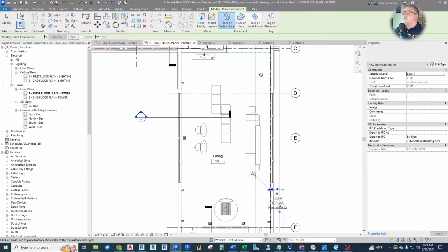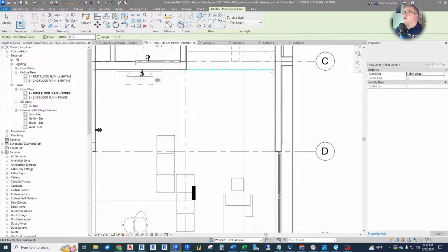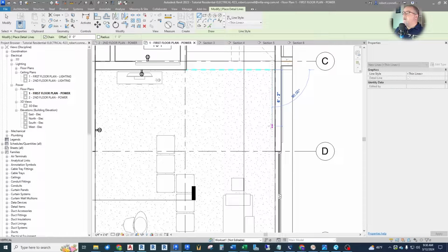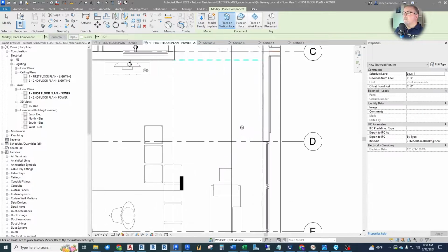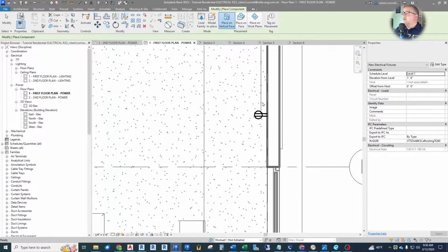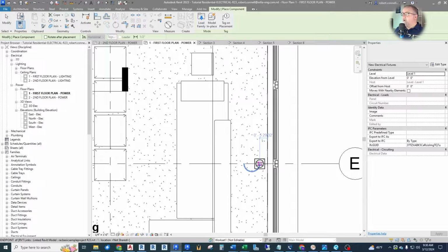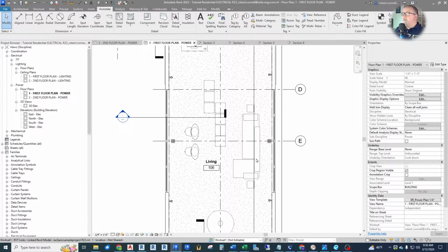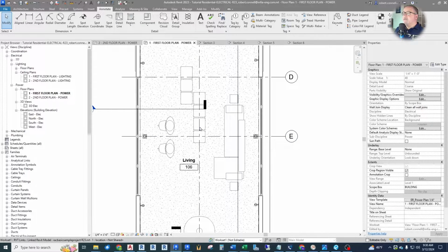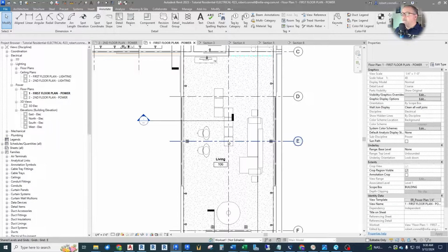We'll put a floor box there. Let's get another. Now this is a different layout. I'd go 6 feet from this step, right at the edge. I think that will still give us 12 feet. And get this floor receptacle over here. So that does the living room. This is all just furniture. Now, if we want to put some floor receptacles in here for tables and such, we sure can, and we may talk to the owner or architect and see if that's desirable. But for now, we'll do the minimum.